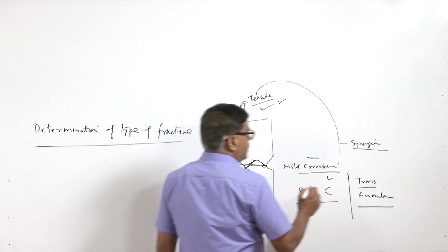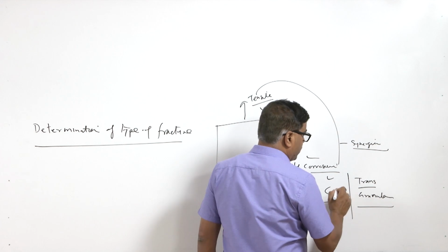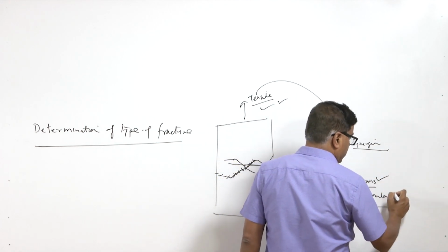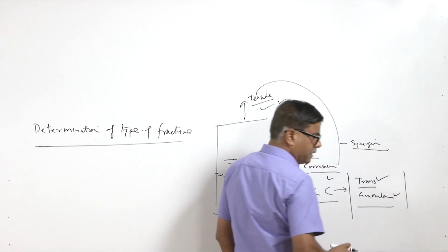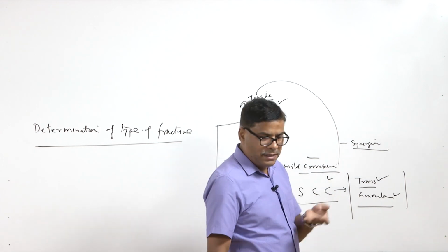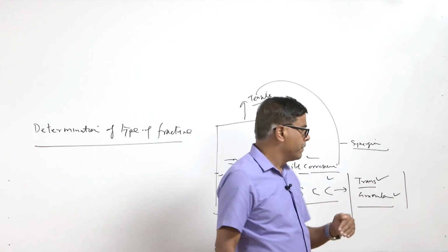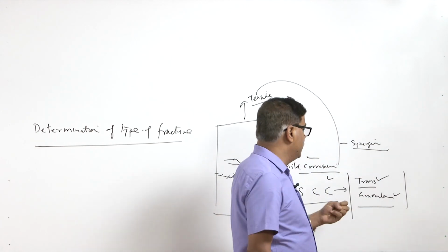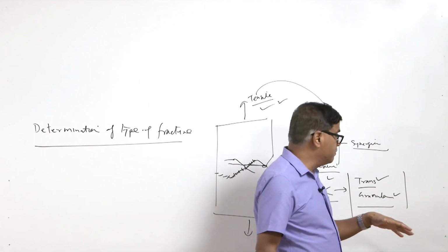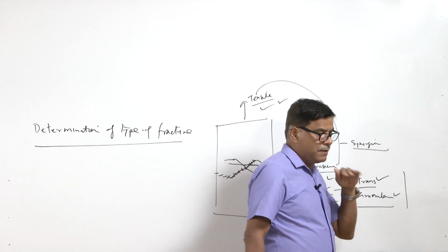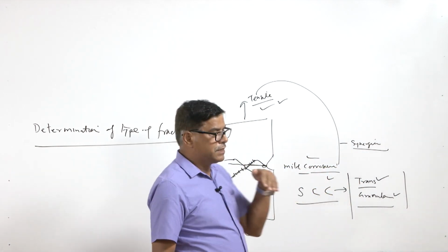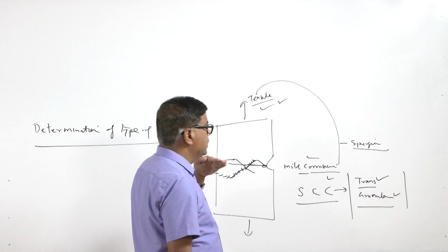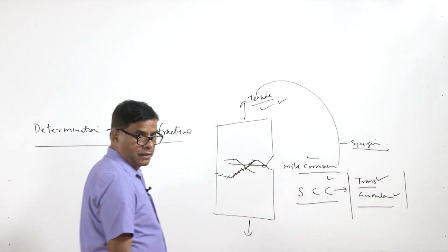So in stress corrosion cracking, crack growth can be transgranular or intergranular as per the kind of weakness of the material. Some corrosive media attack the grain boundaries very badly, while in other cases crack growth is facilitated through transgranular growth of the crack.